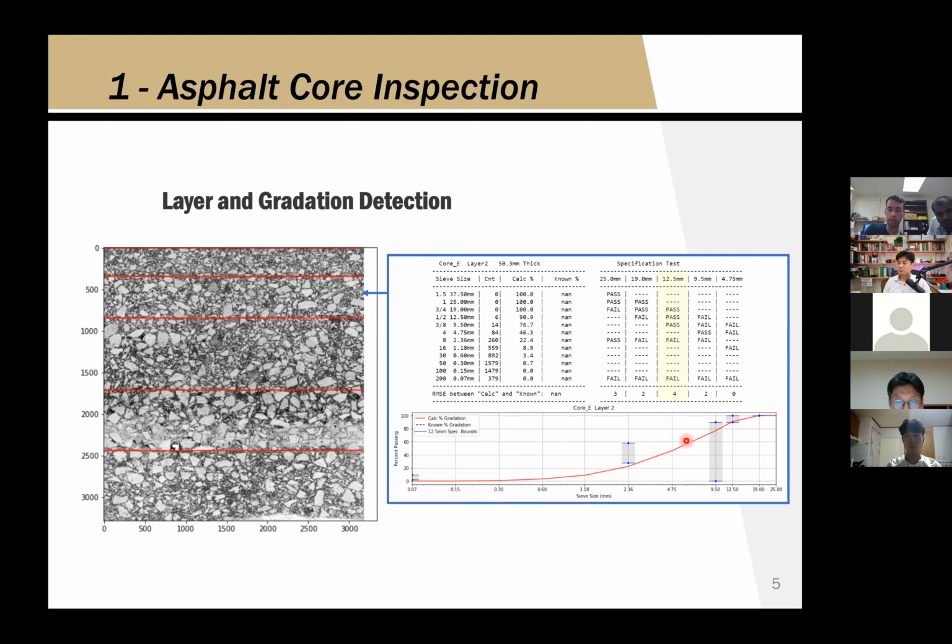And then we would test that to see if it fell within certain parameters. You see these little gray boxes here. This is the parameter that the aggregate should fall through. So that line should pass through each one of these gray boxes. And we used that test to classify the size of aggregate that existed inside the layer. So that's one project that I've done some research on. I'd like to do something a little more recent.